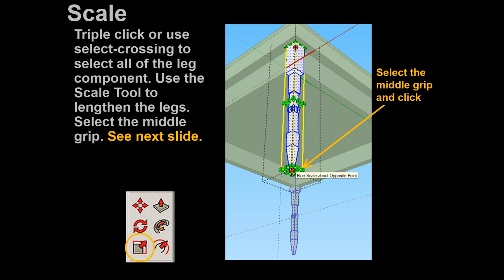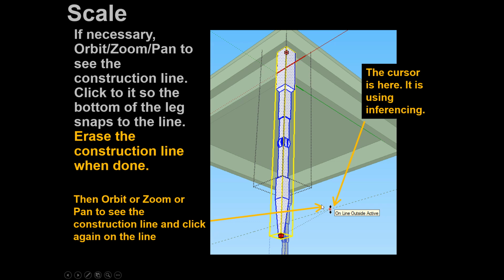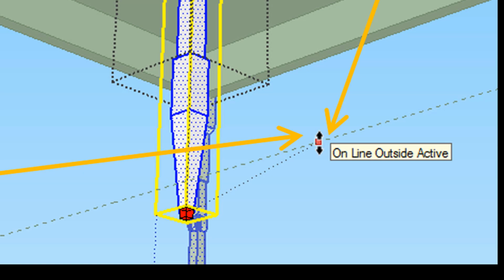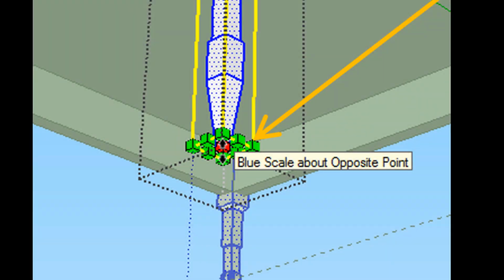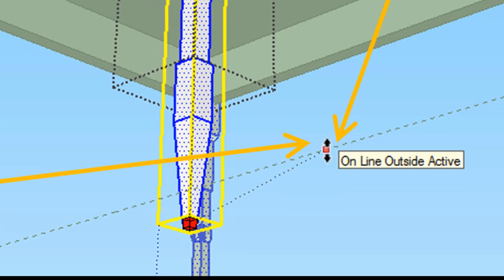So you click to pick it up, no dragging involved, and then you click the line. When you click the line, this thing will just stretch, and it'll look something like this. So let's go back a second. You will click the middle center to pick up that point, and then you'll click the line. Notice the cursor is not touching this dot. I can still move my cursor anywhere I want. But when you bring it down, it should want to snap to this line because it's looking for something to snap to. That's what SketchUp does.